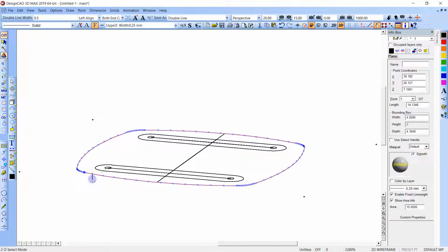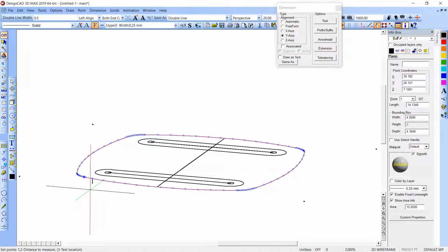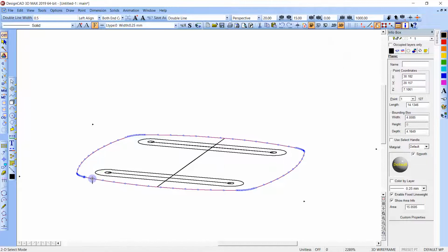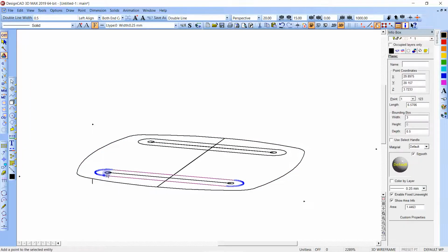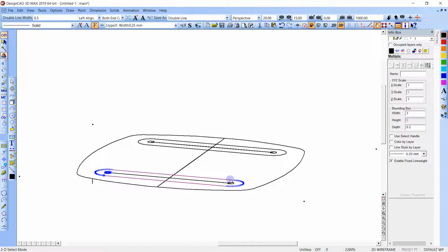I think I've got it. It's to a 1/8 or 1/10, I can't remember. So it's in 1/10, so it's just fine, whatever your thickness needs to be. Then I'm going to hit these. Just select all the lines and holes. I'm going to select V, let's do V, point relative, and shift up, insert, enter.